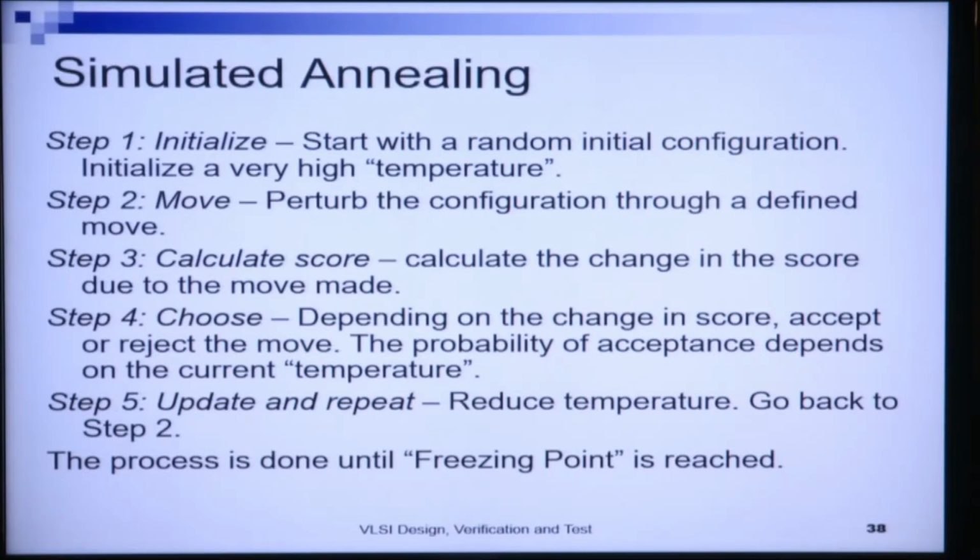Then we generated an initial solution and initial allocation in terms of an allocation of functional units and hardware registers to the operations and registers, and that gave me a cost of the initial solution in terms of the number of functional units required, the area cost of the number of functional units, the area cost of the registers, and the area cost of the associated muxes and demuxes.